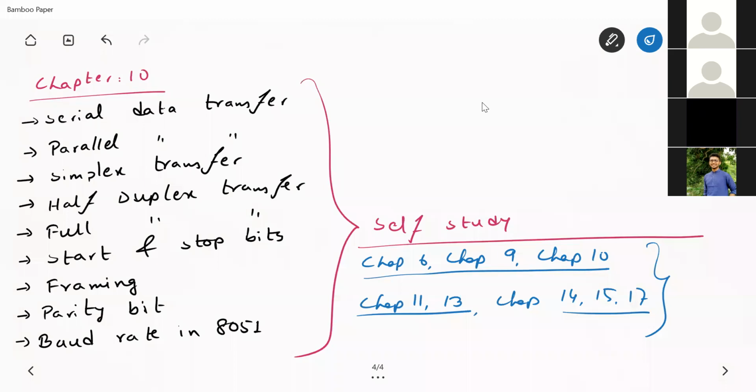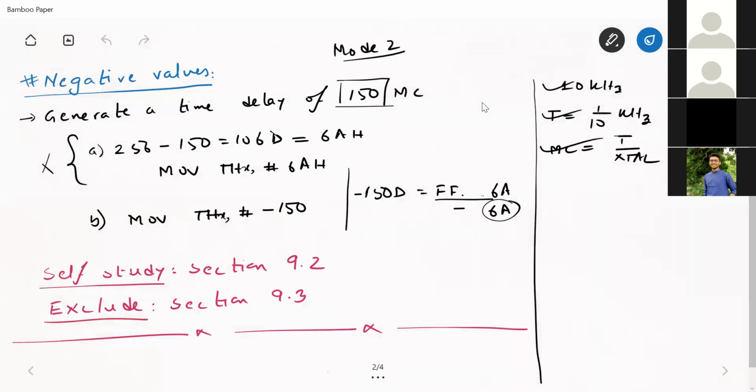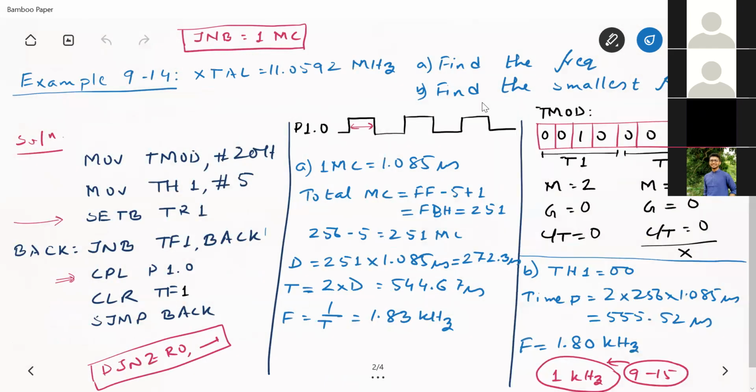I mean, whatever you just said, that is what we discussed over here, right? Yes, sir. Just use another register to control the delay from where you are calling the delay. Then you call the delay for the required number of times. In that way, you can increase your delay, isn't it? Yes, sir. So you can try doing that.